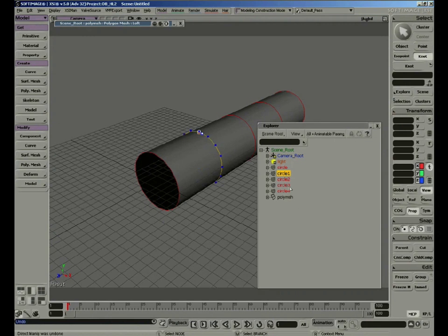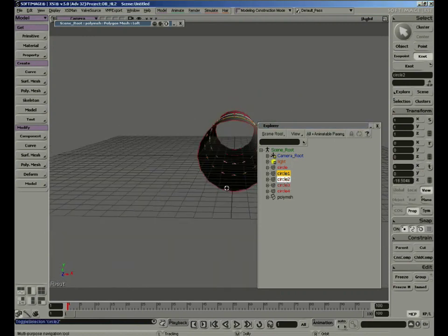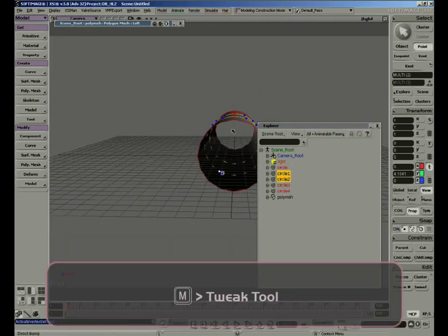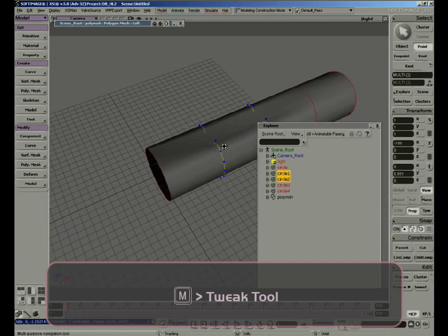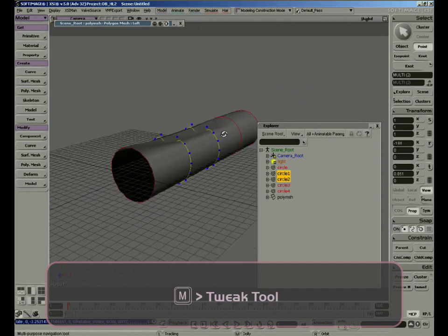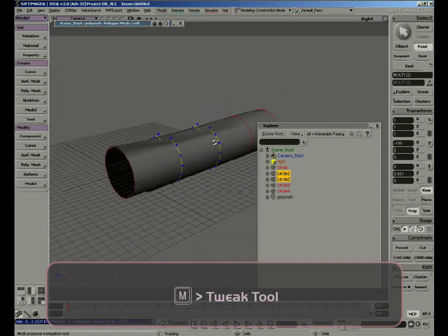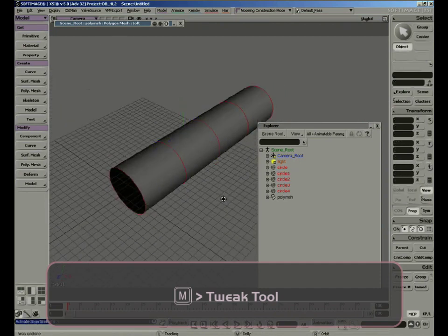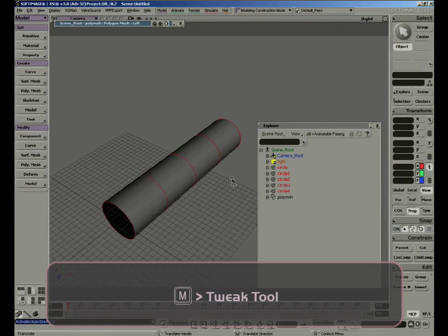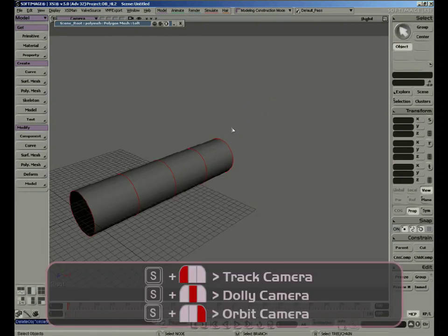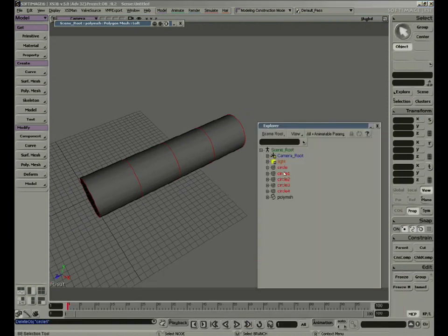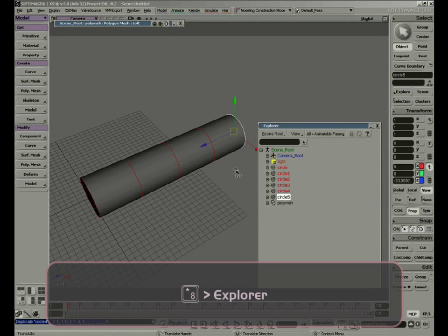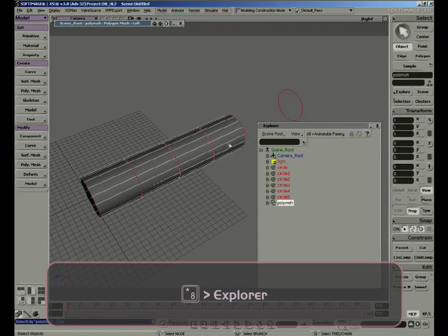And now we have a modeling relation between the curves and the loft or skin. Try taking these two curves and modify the points and continue to sculpt the model. We can also continue to add operators. In this case, we want to continue the loft. Select the last curve, duplicate it, and move. Now explore the created polygon mesh.